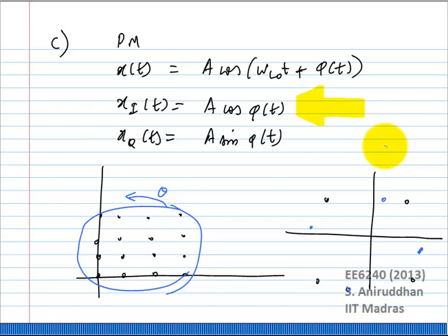Okay, 0.1 part per million is extremely tight. So what I mean is, if you have, let us say, a 20 megahertz reference, 2 hertz is 1 part per million. So you're talking about 0.2 hertz in a 20 megahertz clock. Okay, so it's extremely tight.